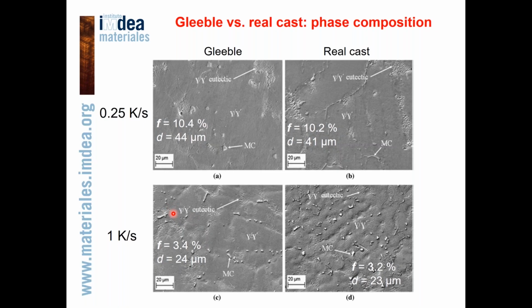Nickel-based superalloys are characterized by formation of the gamma-gamma prime eutectic, which can degrade the mechanical performance of the alloy. This gamma-gamma prime eutectic is a non-equilibrium solidification microconstituent, and its formation is controlled by the chemistry of the alloy and cooling rate.